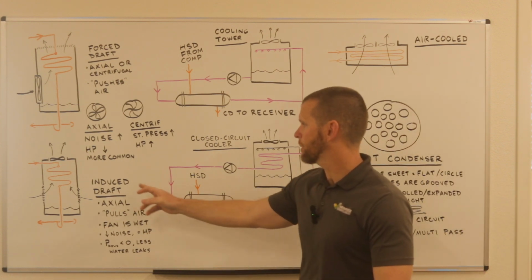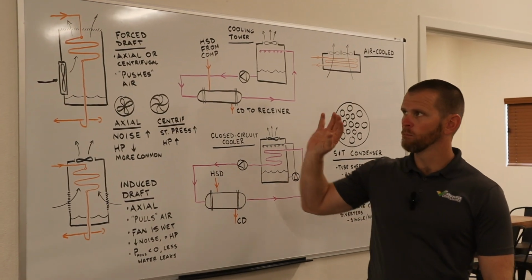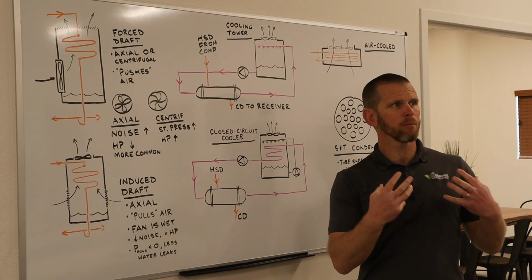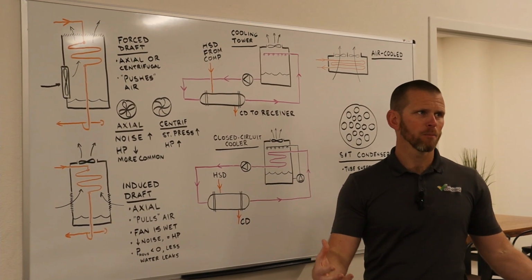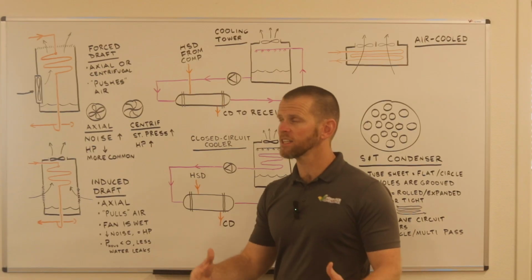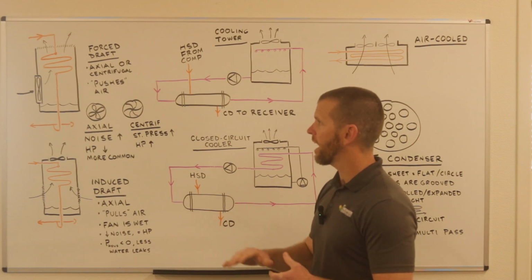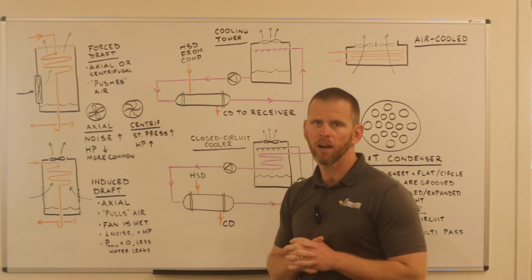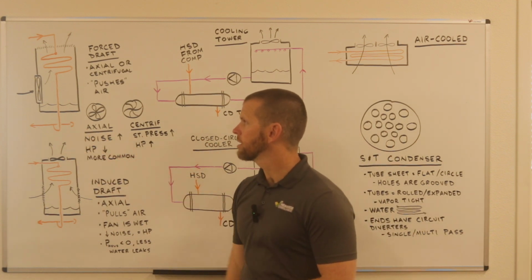And then the evap condenser is basically the best of both worlds because we're using air, we're using water, and by combining both those together, we actually get the most efficient operation. Another really cool advantage of the evap condenser is for situations where air-cooled works, an evap condenser can be operated as an air-cooled condenser. You can drain it of water, clean it out, and just run the fans. In a real cold climate or situation where air would work, evap can double as an air-cooled condenser.